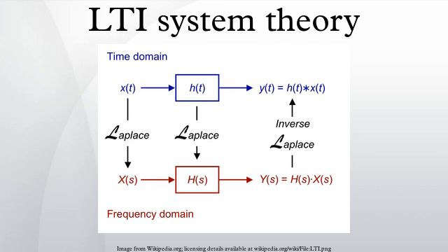Z in discrete-time Fourier transforms. The eigenfunction property of exponentials is very useful for both analysis and insight into LTI systems. The Z transform is exactly the way to get the eigenvalues from the impulse response. Of particular interest are pure sinusoids, that is exponentials of the form e^{jωn}. These are generally called complex exponentials even though the argument is purely imaginary. The discrete-time Fourier transform gives the eigenvalues of pure sinusoids. Both of H(z) and H(e^{jω}) are called the system function, system response, or transfer function.